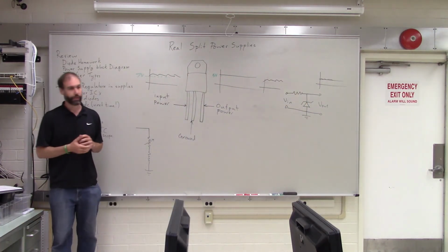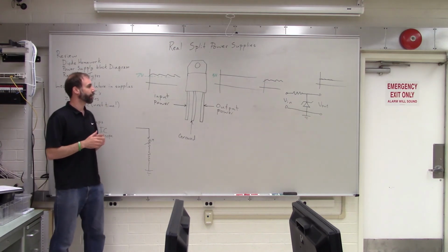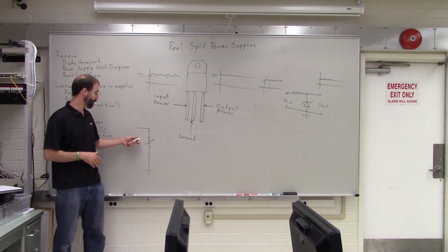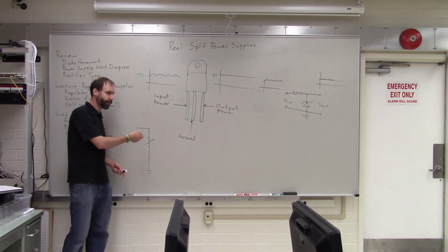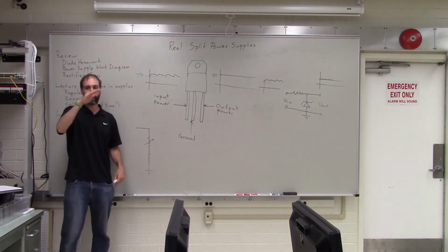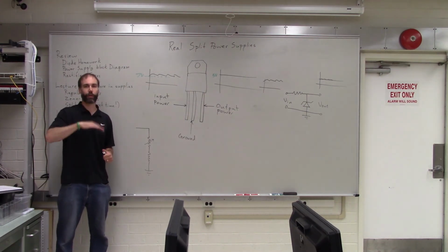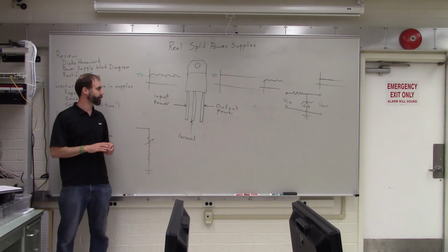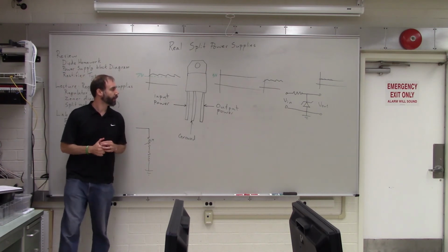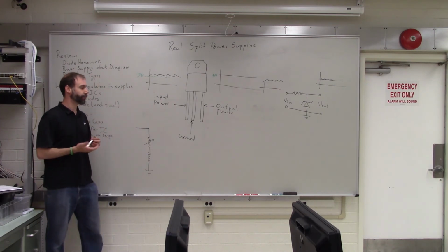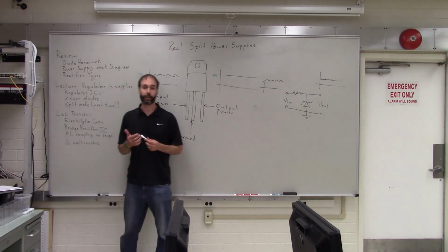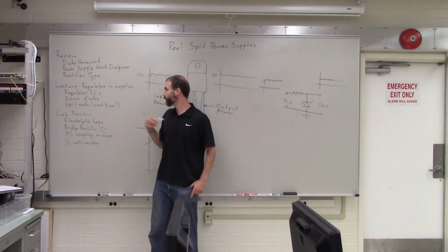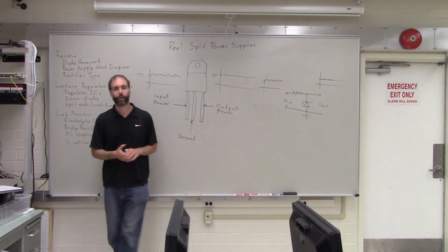Okay, so those get turned on and off, and so instead of having a little resistor that just gets dialed up or down, you turn the output on and off and on and off and on and off really fast, and it kind of averages out to a nice flat signal. So we'll talk a little bit about that next time. Yeah, really fast. Any questions about that before we go and talk about our lab?